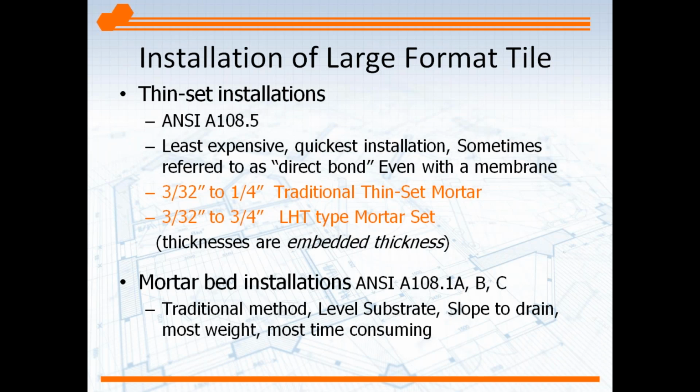And what would happen with that mortar is it was not designed, it was not engineered to go in that thick. So it was slumping away from the tile overnight, among other things. The one to think of is it was slumping away from the tile overnight. And as it slumps away from the tile, it debonds from the tile. And obviously that was not suitable.